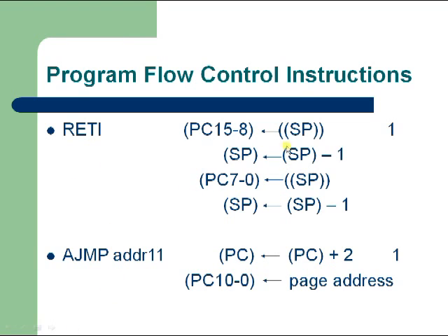Now RETI is used for returning the control from the ISR, the interrupt service routine. The same operation goes on: the value pointed to by the stack pointer is copied into the higher byte and the stack pointer is decremented by 1, and again the value pointed to by the stack pointer is copied into the lower byte of the PC, and it is decremented by 1.